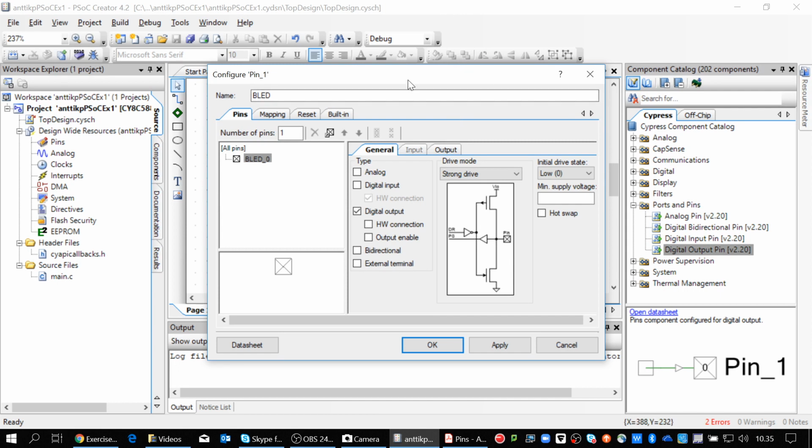In an old school design, you would always put this LED tied up to the power and use a pulling down kind of drive. But as I said, it would be an old school design. Usually these processors or other devices have better drive as a sink than as a source. Let's put it this way. So this far we have strong drive low, initial drive state is 0, so it doesn't blink unless I tell it.